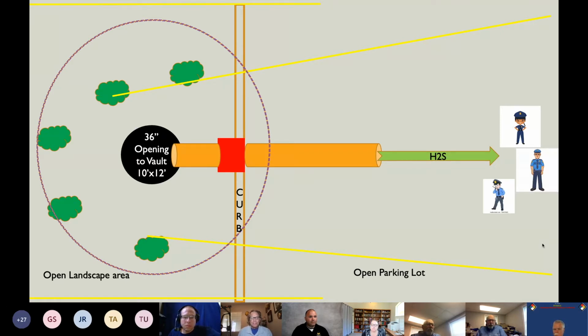I thought that a visual indicator of caution tape meant everybody stays out, but it not necessarily does that. So in addition to putting up our exclusion zone and our visual indicators, we have to monitor that and make sure nobody decides to go in there and do some business. And actually, I had to walk over there and tell them to exit, which they did after some concern when I told them that the stuff we're venting into this area is the stuff that killed the 2 people in the hull. I had to get that basic with them.